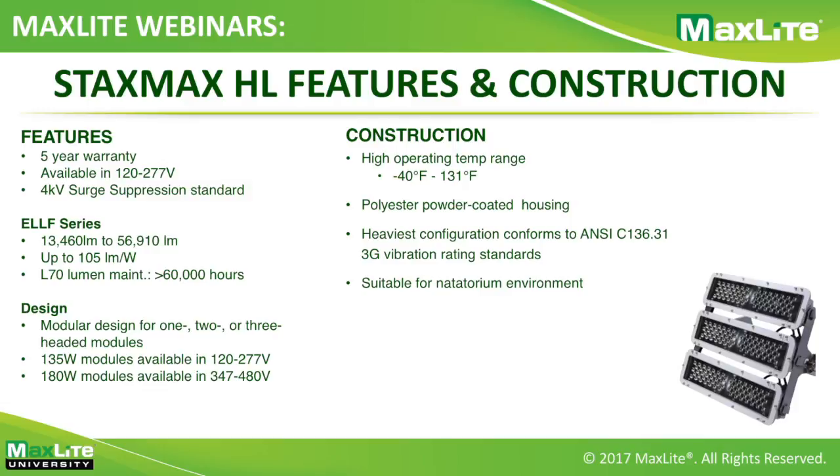It does go up to over 56,000 lumens with up to 105 lumens per watt, and it's a modular design for 1, 2, or 3 headed modules depending on your location. It has a high operating temperature range, 131 degrees Fahrenheit, and the heaviest configuration conforms to the ANSI C136.31 3G vibration rating. And it's also suitable for a natatorium environment as well. This is actually true of our Hazlock series and also the standard STAXMAX.